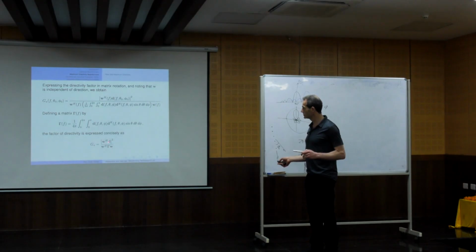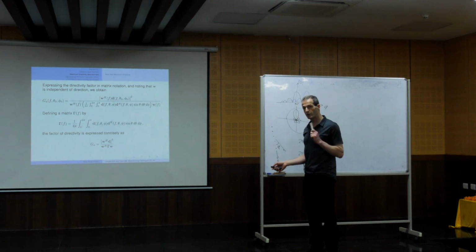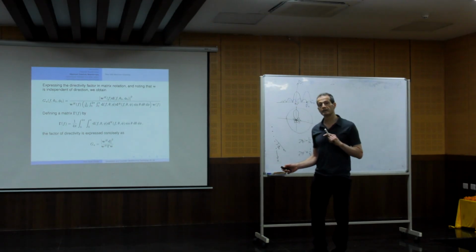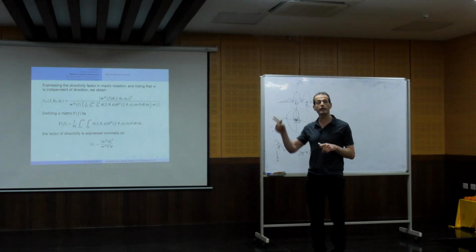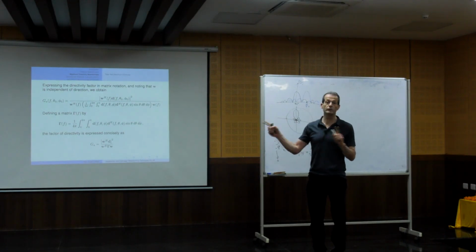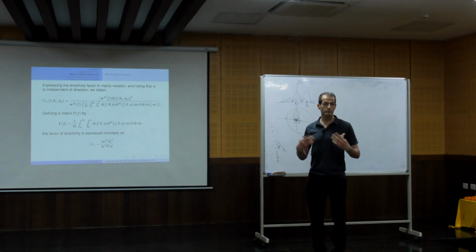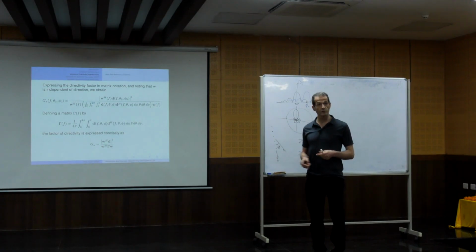Now, suppose that this ratio is high for a certain frequency. Is it sufficient? It maximizes the directivity for that frequency. But also, very important, the gain, the numerator, must be independent of frequency. Why? Because if it depends on the frequency, it means that we have different gains for the desired source at different frequencies. So this is a distortion. It's like distorting the desired source.